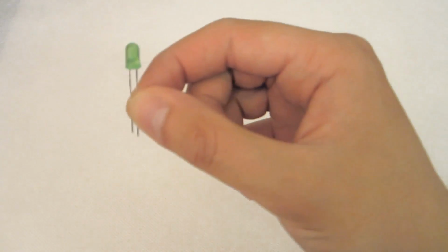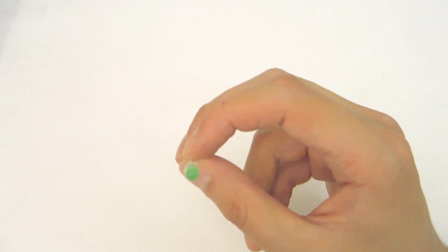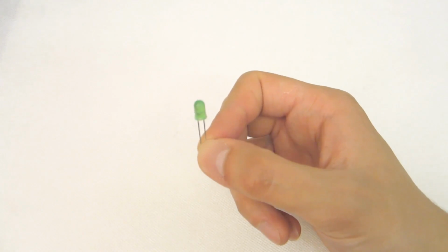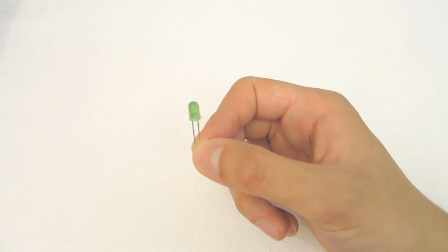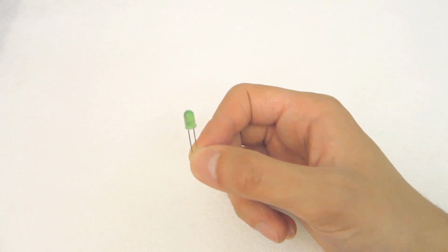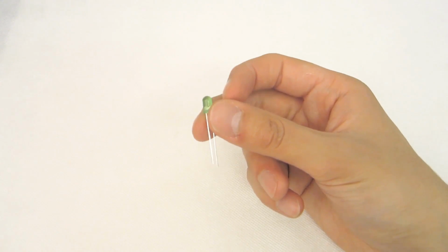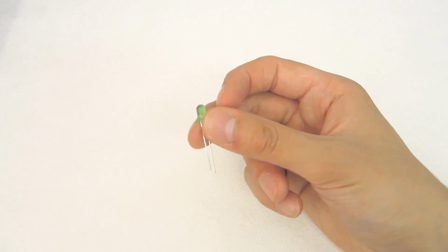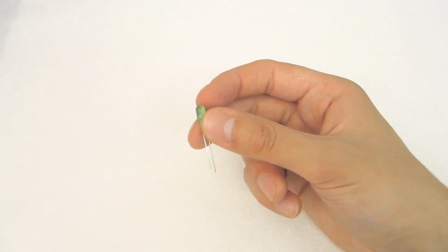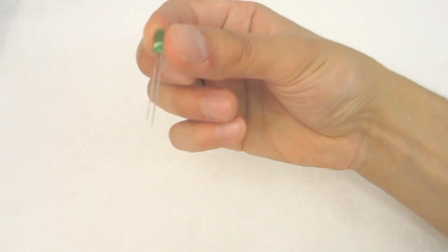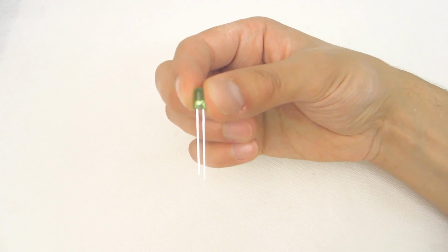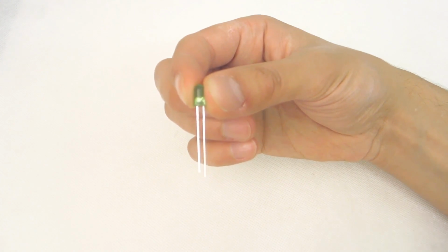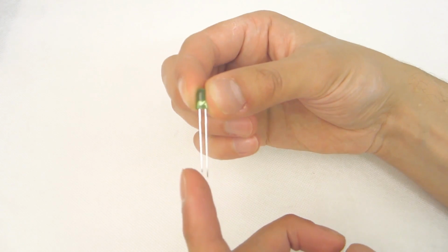Now, LEDs don't really have labels, but this, as you can see from the stars, is a standard 5mm LED, which is often used in electronic projects. LEDs, as with any diode, have a positive and negative terminal, and they need to be hooked into the circuit correctly or they won't work properly. So with an LED like this, there are two basic ways to tell which terminal is which. If you can see, there are two legs here.